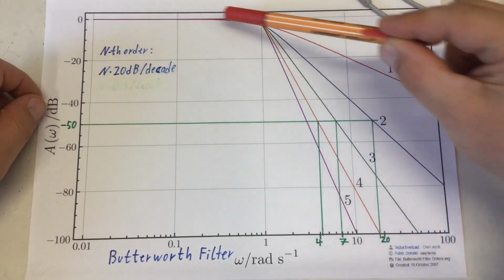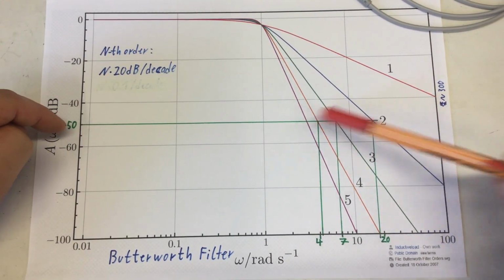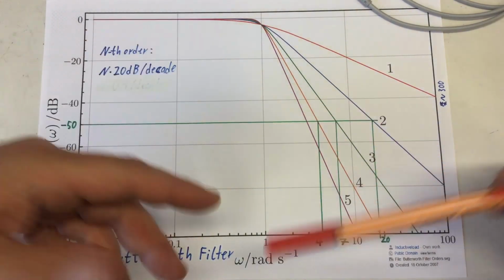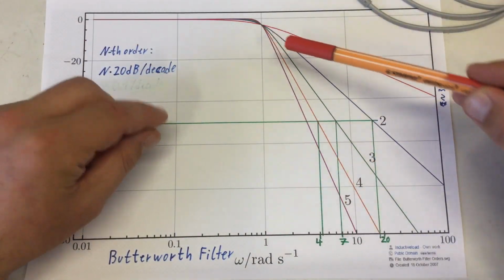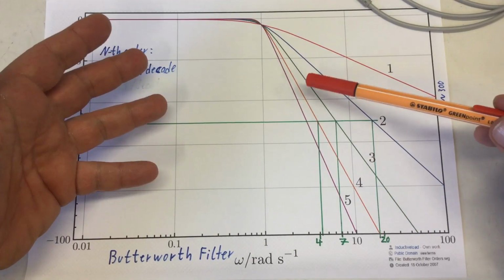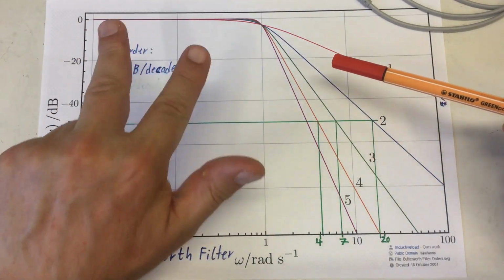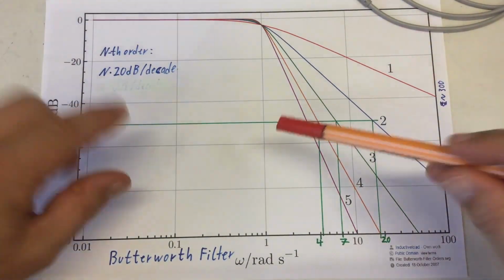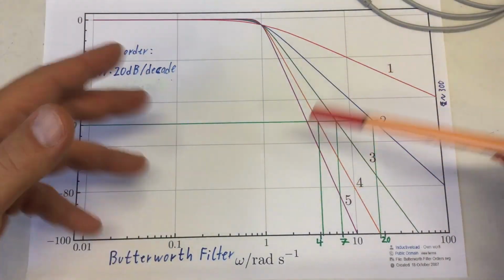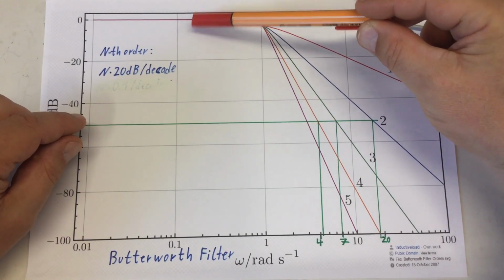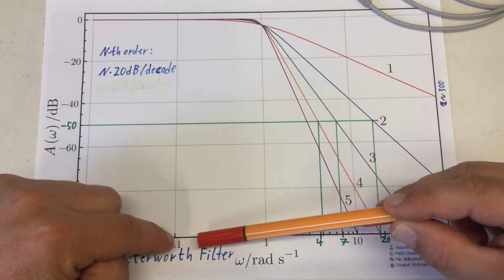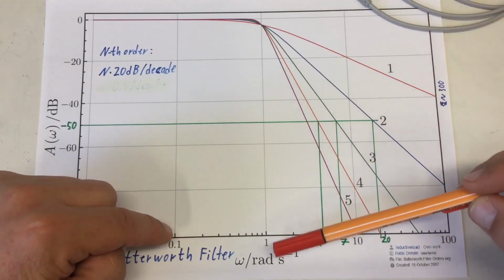The line for the first order filter would intersect with our minus 50 dB line at about 300 out here on the frequency scale, meaning our cutoff frequency for PWM signal of 980 Hz would be about 3 point something Hz. In addition, the curve of the first order filter deviates quite early from the 0 dB line at about 0.2 of the cutoff frequency.